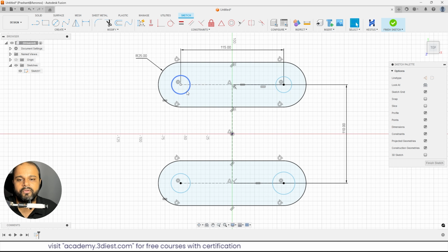So we'll go back to our Fusion. First, I will go back to my design tree and turn on all the default planes we have. So these are all the planes we have. In this case, we'll be creating the circle on this plane. To create that circle, again, we'll start from the sketch. We'll activate this create sketch tool, then select this plane as the sketch plane. On this face we want to create our sketch, so we'll click on it.